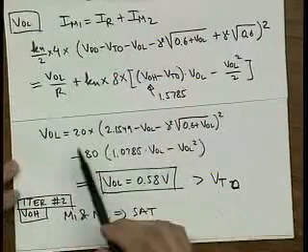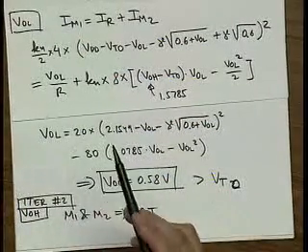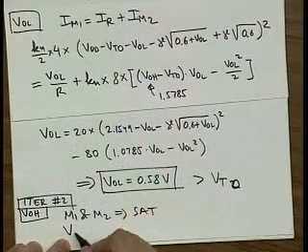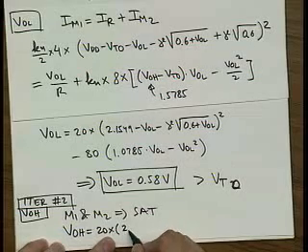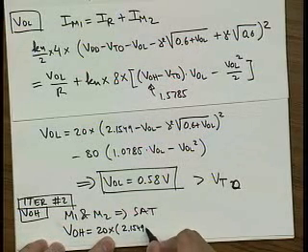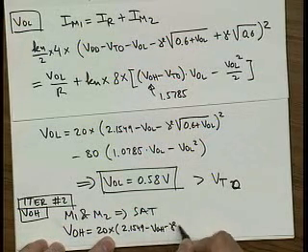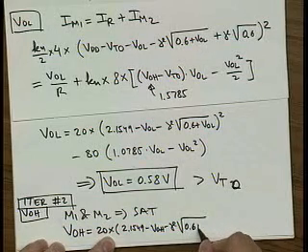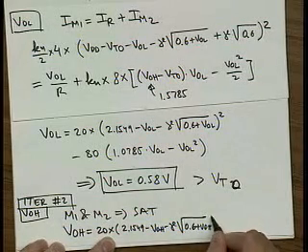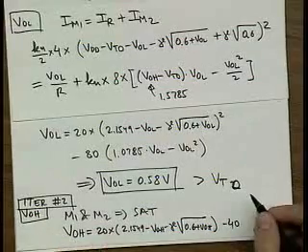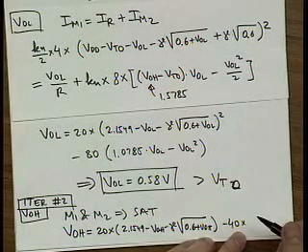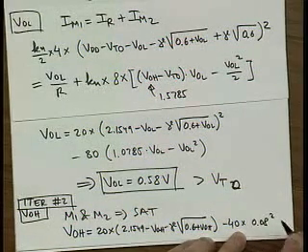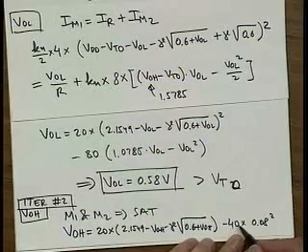And then you work with the saturation currents to get VOH is now 20 times 2.1549 minus VOH minus gamma times the square root of 0.6 plus VOH, and then you have minus, from the bottom transistor, 40 times VGT squared. It's basically 0.08 squared, and this was because 80 divided by 2.